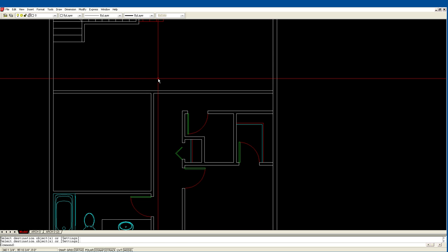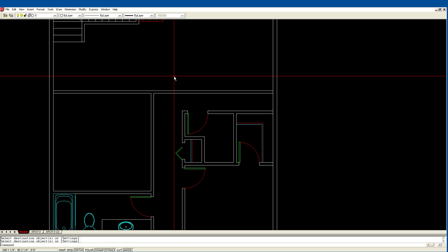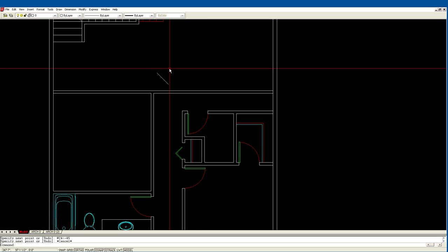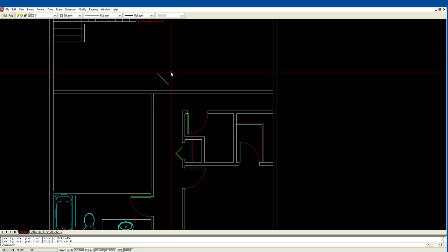70 inches. So first thing I'm going to do is I'm going to draw a line. Okay, and from that I'm going to go 24 inches, and then I'm going to tell it what direction. I'm going to press less than, which is telling AutoCAD which direction I want to go. And it really doesn't make a difference how you do this, but I'm going to go minus 45, and there it is. Okay, now this is just going to be a little bit of playing around.